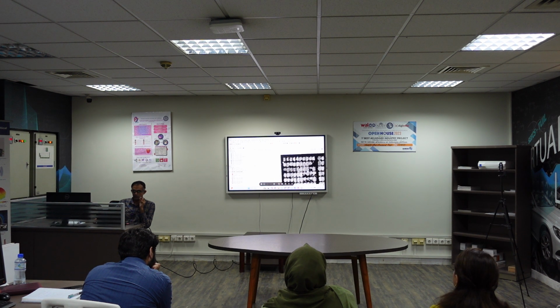So we want to ensure that a particular point we are sampling has to be sampled as if it is sampled from a solid portion of the digital surface model. Because your digital surface model is actually not very accurate due to its inherent limitation that lies in the photogrammetric processing.